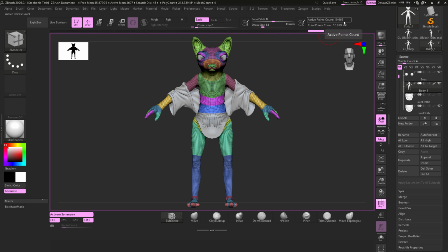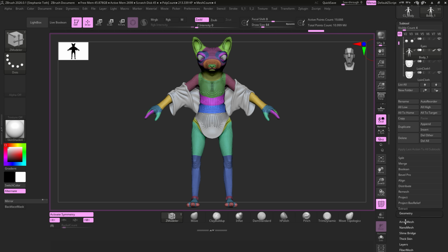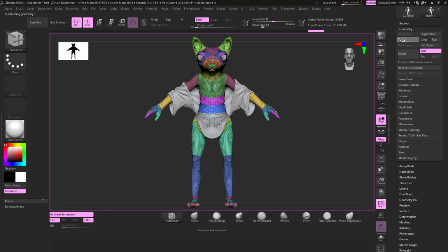I think that's a really solid amount. Definitely enough for deformation inside of Maya for when we animate. I think somewhere in the 13 to 20,000. You can probably even aim for 10K if you wanted to, but that's probably the range that I would go for. So if you needed to, you could go up a subdivision level to like subdivision level 2 and just export from this level.